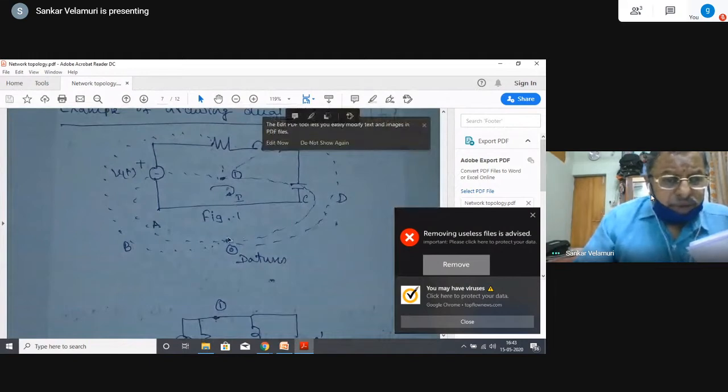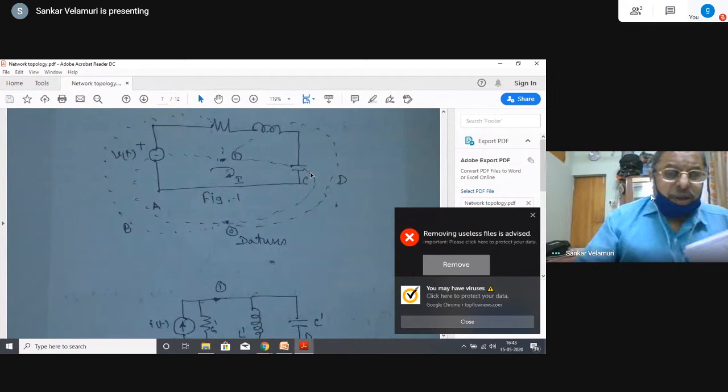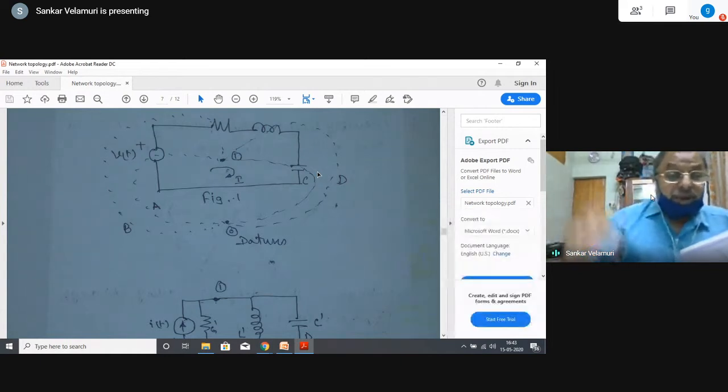So place the dot outside the circuit and place the node corresponding to the loop. There is only one loop, so place only one node. Now for each node you traverse like this, from node to this capacitance to node. So this capacitance will be changed to inductance. What are the equivalent values? There are problems in this also, though not many times are the problems asked. That is a topic by itself. I need another one or two hours to explain how to calculate the dual network elements, equivalent values, and other things.